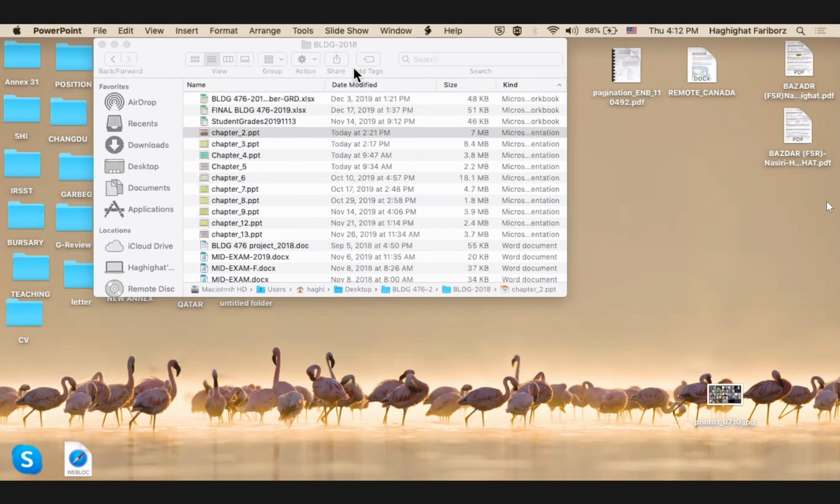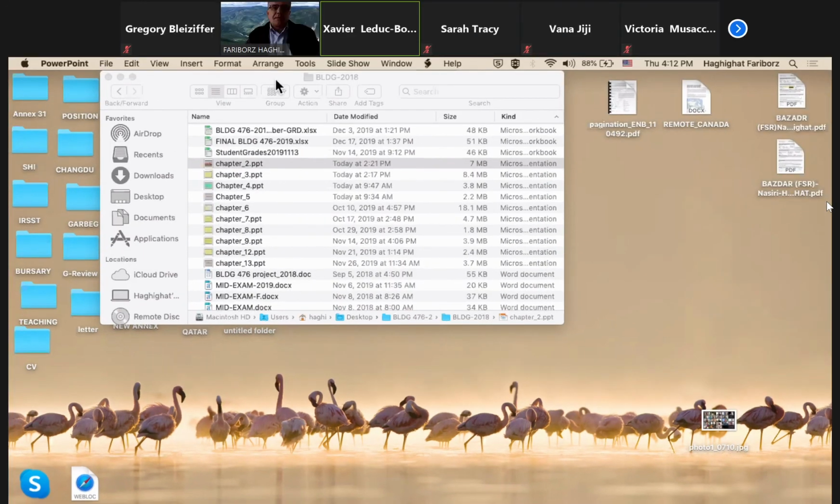No, you're right. All the energy going to that point is equal to 0. All the energy meaning, like, the solar radiation from the window. Therefore, if this is the surface of your floor, you write the energy balance for this one. You have conduction to the ground, to the soil, you have convection to the room air, and you have some solar radiation coming to that one. All of them equal 0.